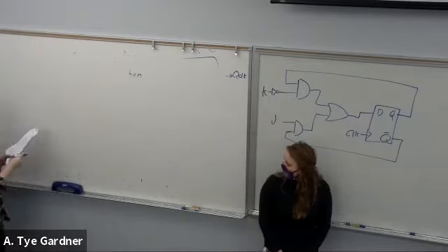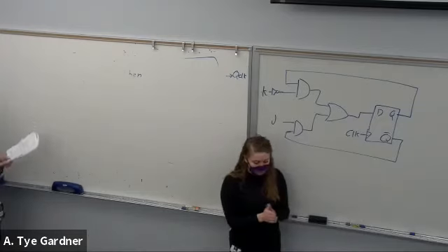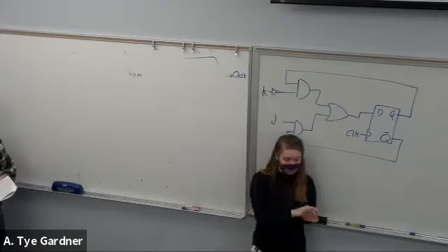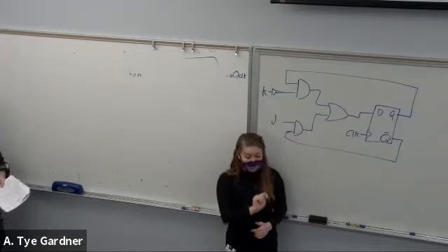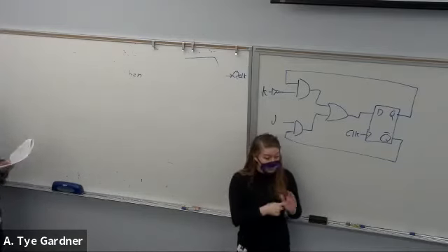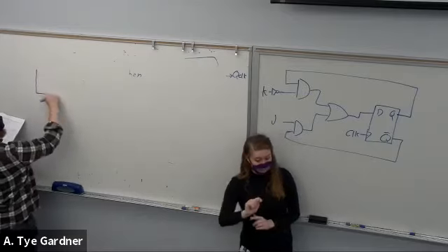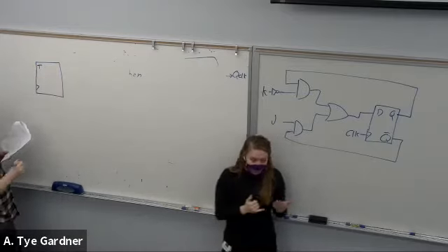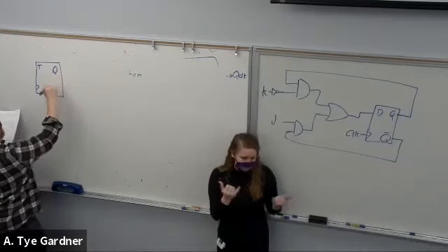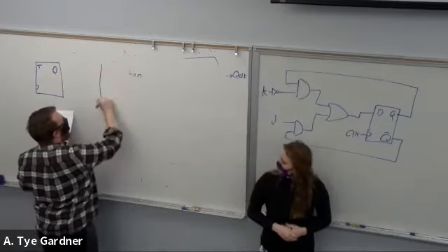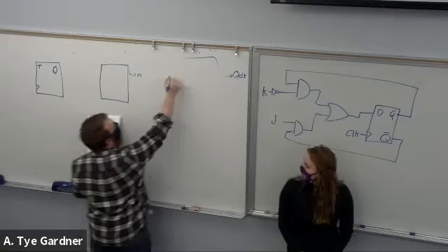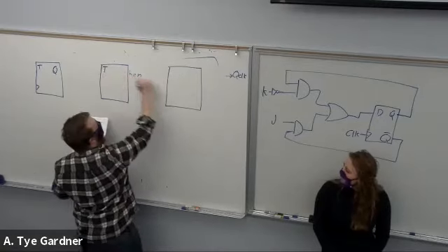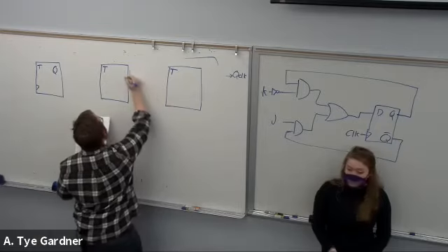Next up, we can build what is called a counter out of using T flip-flops. So I've shown you the VHDL for the T flip-flop. So when I draw a T flip-flop, you know what that VHDL is now. So I'm going to build a 3-bit counter.